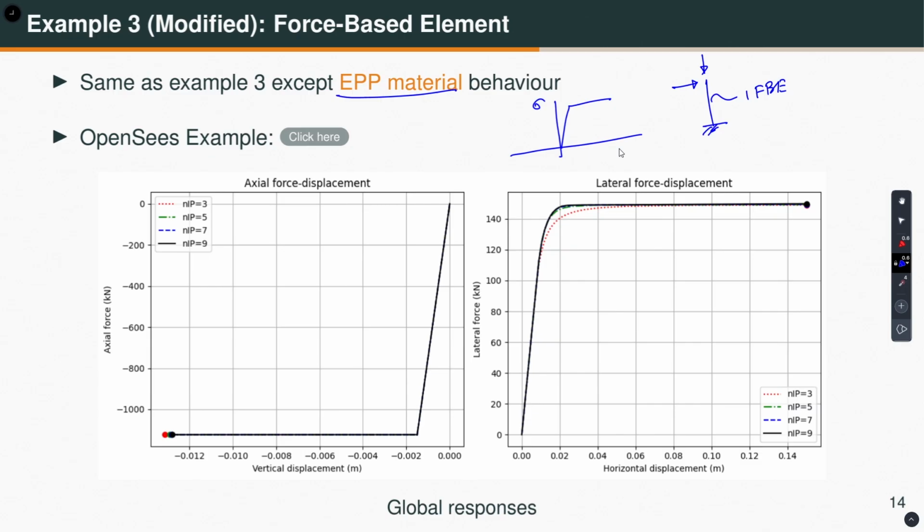So this is my sigma epsilon response. Earlier, I had a strain hardening ratio of alpha equal to 0.005. Okay. Now, I am not giving any reference solution for a reason that you will see in just a little bit. So, as I did earlier, I was increasing the number of integration points and studying the convergence of solution, the global response and the local response.